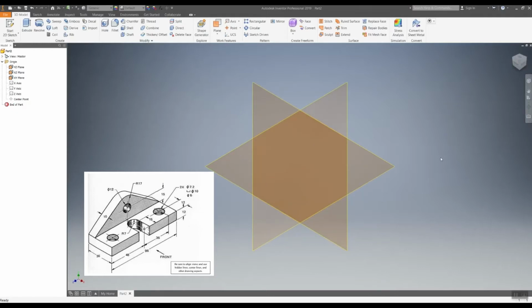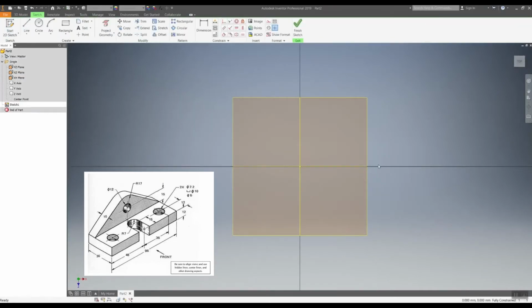So as I said before, I have this bottom feature over here, and I think I want to extrude that straight up. And then we have this back feature over here, and I'm going to extrude that front. I think doing the top feature will be the easiest first. So let me go to Sketch. I'm going to go over here. And I'm simply going to draw this box.